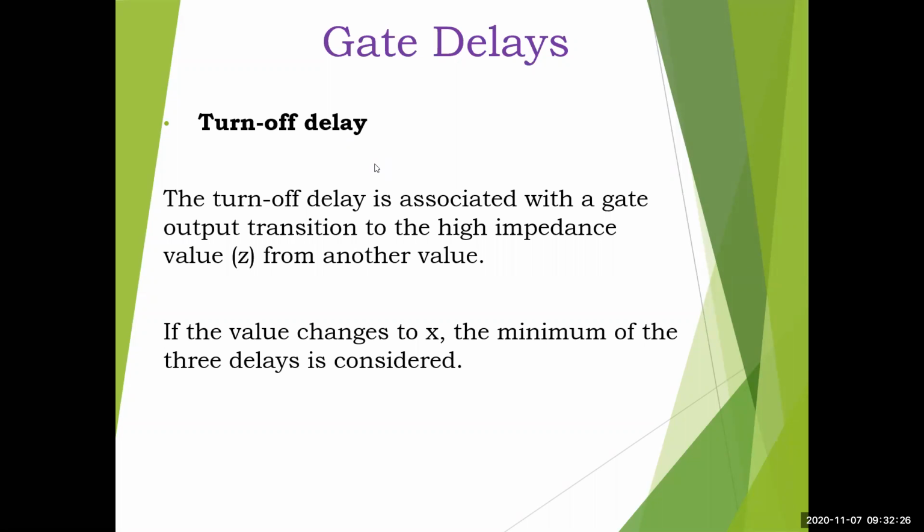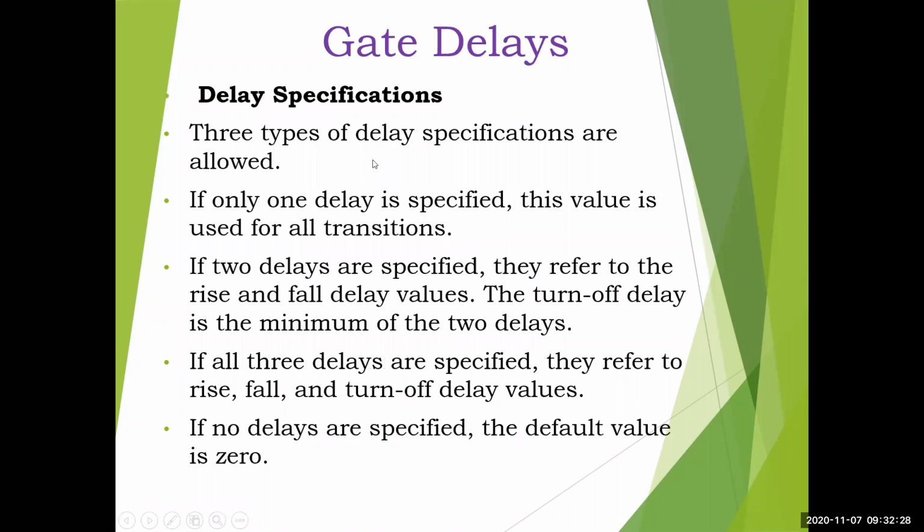Okay, we'll see that. This is called delay specifications. There are 3 types of delay specifications allowed in Verilog. If only one delay is specified in a gate transition, this value is used for all the transitions.